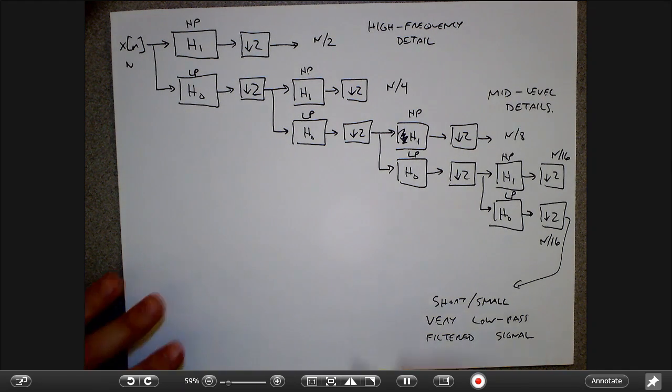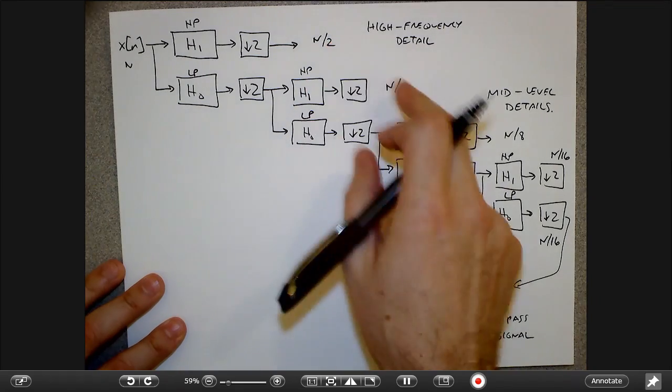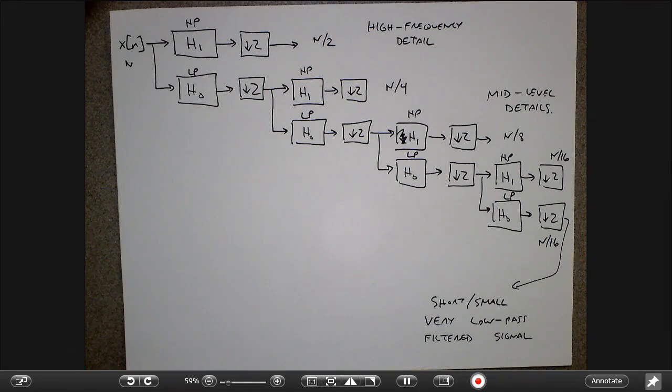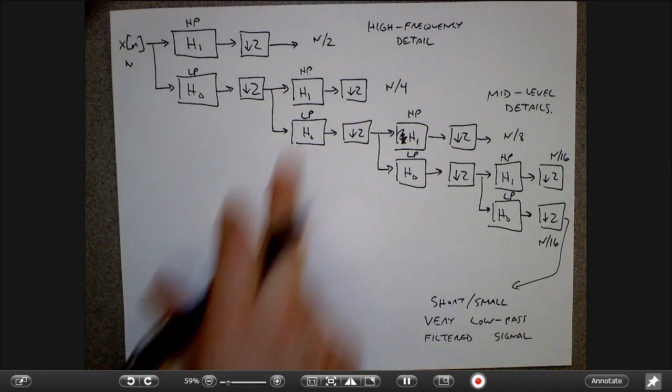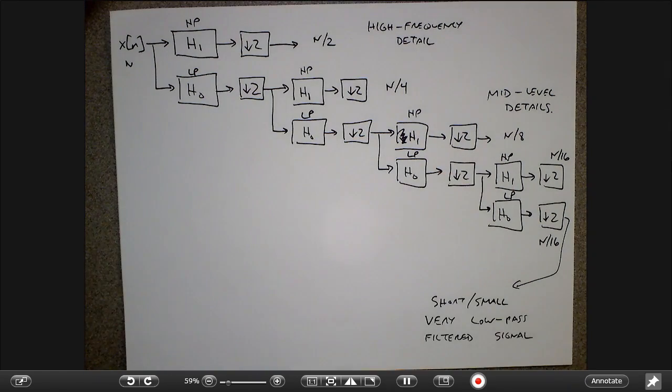So the idea would be that I would put all these through some sort of compression algorithm, which is related to the quantization stuff we talked about last week, where I would quantize these coefficients at various levels, and that would hopefully make my signal a lot more compact, so that when I reconstructed it on the other side from these quantized coefficients, I would get something that looked pretty much like the original signal, but it would use a lot fewer bits, right?